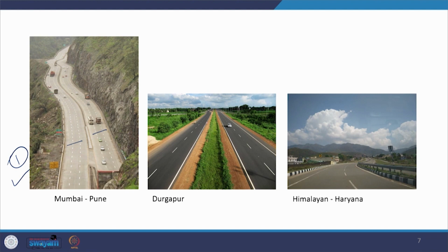In the center, the median is not wide, it is a flush median which will be taking not more than say 4.5 meters width of this particular road section, and then at the end a parapet wall is provided, so as to provide a psychological safety feature to this particular section as well as to the drivers who are driving their vehicle on this section.